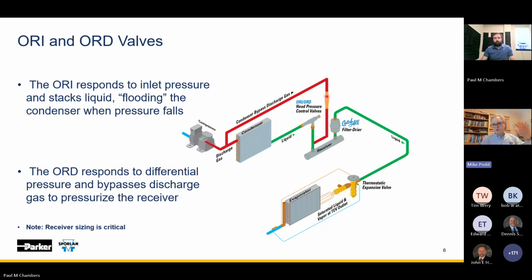So these valves work in conjunction. They work together to keep the pressure entering the expansion valve up into its operating window. And in doing so, this ensures that there's enough refrigerant volume to do the work in the evaporator and to keep that compressor operating in its design window as well. So that's the benefit of these two components in conjunction.